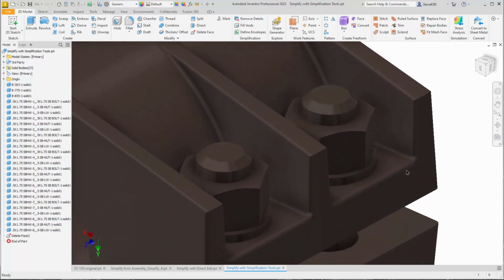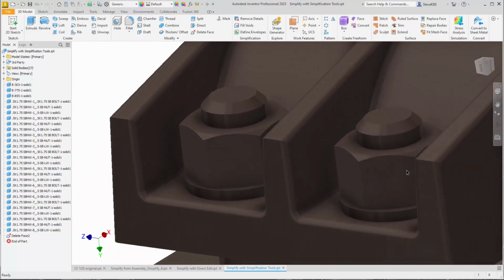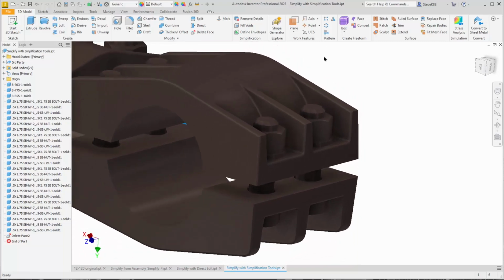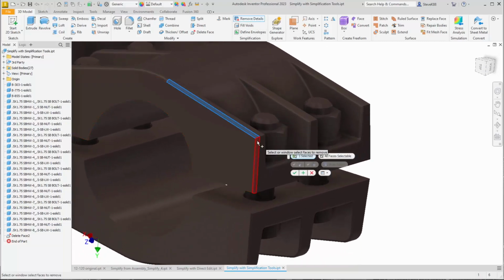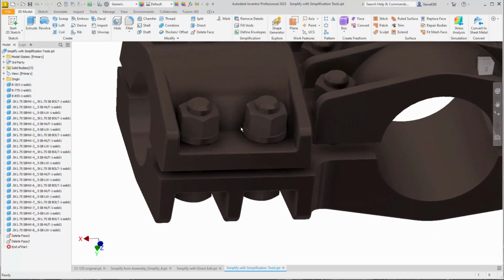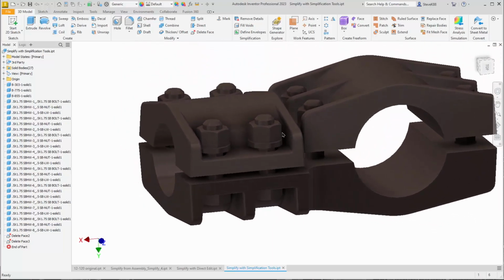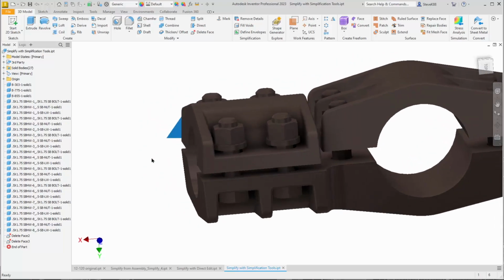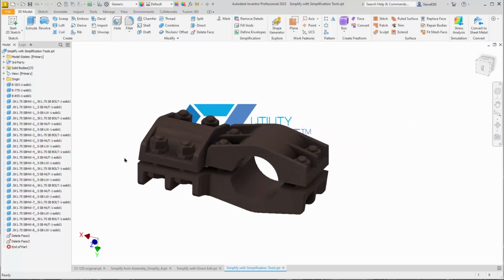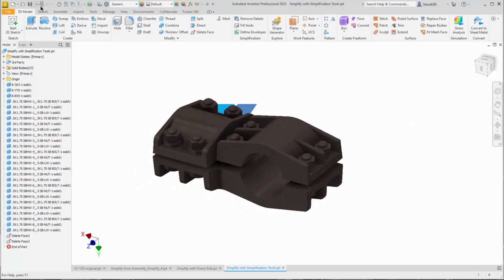And you can see I was able to replace those items and just have a regular chamfer. My next point, I'd have to go through again, kind of like the direct edit tool. I'd have to just keep replacing pieces just like that and say OK, and I can pick multiple pieces like that. What we can also do is do a number of items by selecting a window, but it's got to be compatible with selecting that window, just like direct edit. So with that, you'd have to pick all of those items.